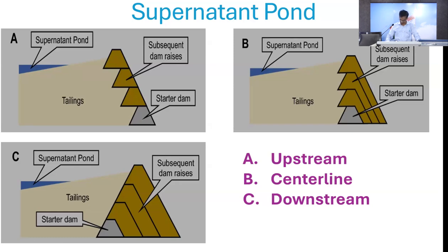So you don't have an option there, and mostly that becomes a boundary also, your land boundary. Where we did not get any land outside our dike, we go with upstream raising. When we got land outside our dike, we go with downstream raising. Yes, that is the reason. So that's why what I was talking about, water management of this tailing becomes difficult due to our approach of starting the dike from our boundary.